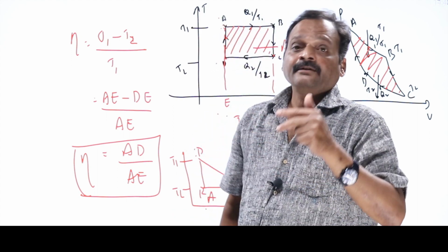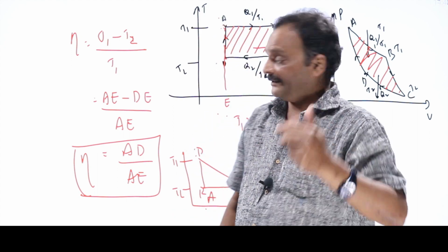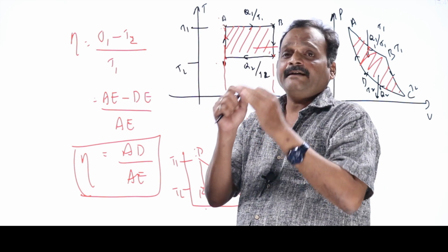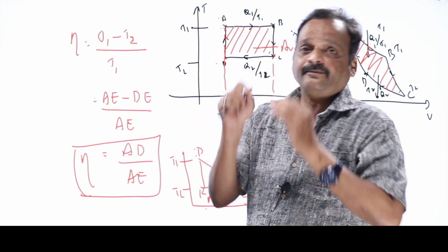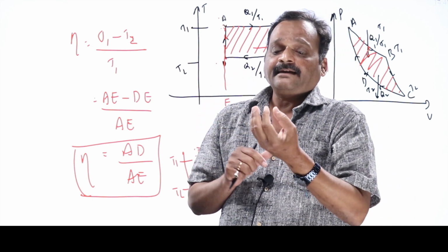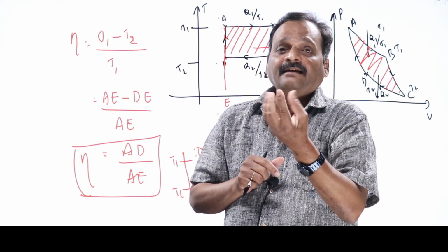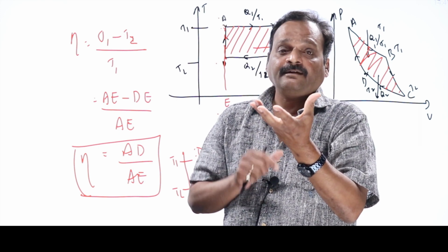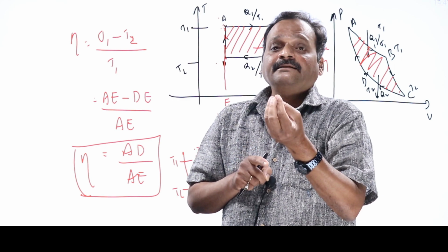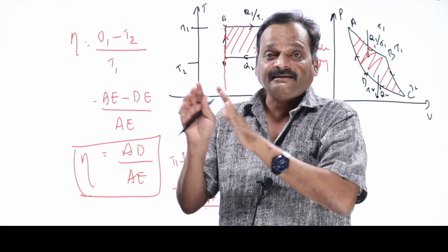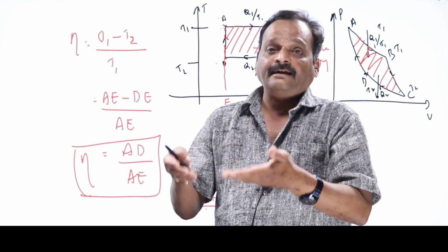Now we'll go into the first energy equation, which is extremely crucial from all entrance points, not only from the subject point of view but the concept point of view. From it I can understand how internal energy of a real gas varies with volume, that is, how internal energy varies with pressure at constant temperature for a real or van der Waals gas.